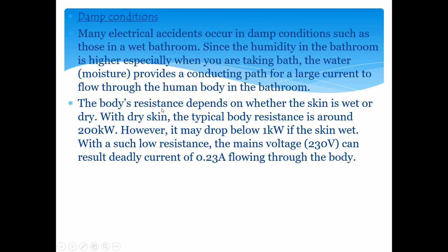Then damp or moist condition. When we use electricity in a damp or moist condition, that can also be dangerous. For example, water alone is not a good conductor, but if your hands are wet or moist and you touch the electrical socket, a small amount of water can conduct electricity, and that may lead to electric shock. So many electrical accidents occur in damp conditions. Dry skin does not conduct electricity as compared to moist skin.